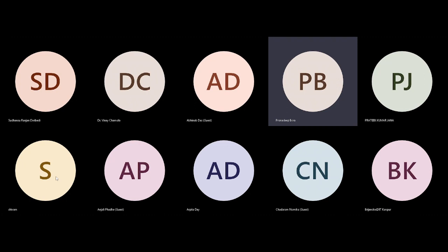So let's say in simulation my design is working, but in implementation my design is not working, and my design is huge. What can we do? I can see net by net, leaf cell by leaf cell. But these are only small codes, right? If you are implementing a microprocessor or an 8-bit microcontroller, it will have many components, so this method will be very difficult. That's why we should know while coding how to code properly so that the tool will infer the right kind of resources. If I'm not confident in my coding, I should use IP code.